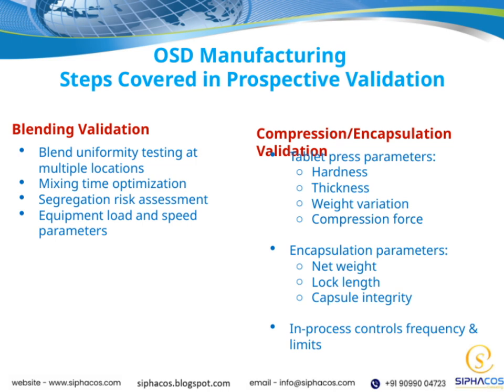Switching gears to encapsulation, we focus on parameters like net weight to guarantee each capsule contains the correct amount of active ingredient, lock length, which ensures capsules are properly closed, and capsule integrity, vital for preventing leakage or contamination.